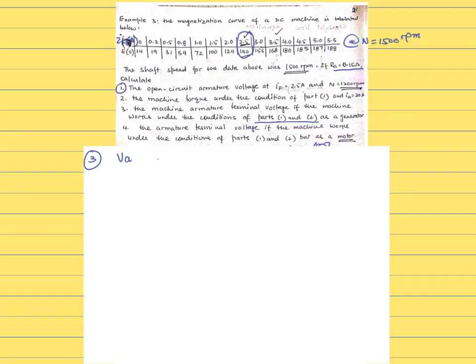What we mean by that is we have IF 2.5 amperes, we have speed 1200 RPM, we have E 111.83 volts or 112 volts, and IA was given in part 2 as 20 amperes. So it's saying working as a generator. So this is how it's going to work as a generator.